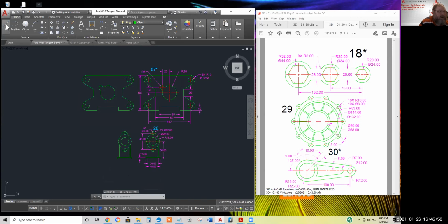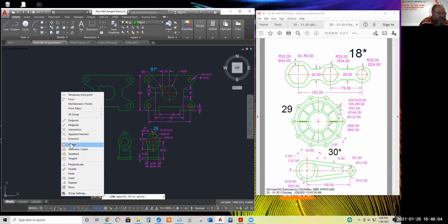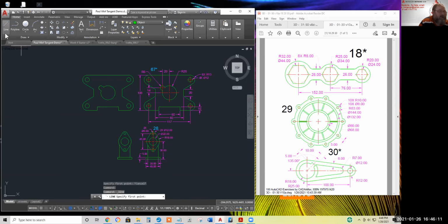If you're quick with a keyboard, you can hold the shift button and right click and select the one-time use only OSNAP override. I'm sorry, if you're quick with a typewriter, type the override like NEA for near. All right, what happened? Somehow I got into dimensioning.